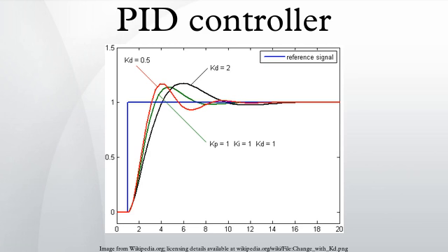In particular, the inner summation produces a new single error value which is compensated for future and past errors. The addition of the proportional and derivative components effectively predicts the error value at the derivative time in seconds in the future, assuming that the loop control remains unchanged. The integral component adjusts the error value to compensate for the sum of all past errors, with the intention of completely eliminating them in the integral time in seconds. The resulting compensated single error value is scaled by the single gain.